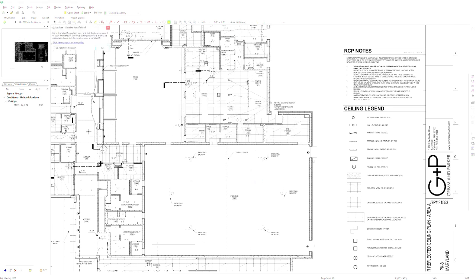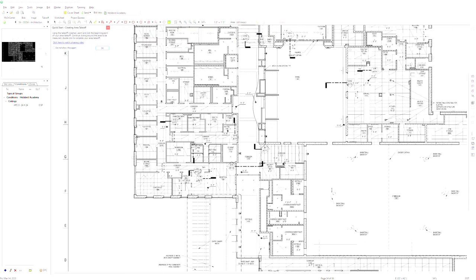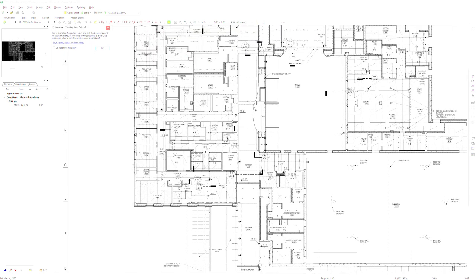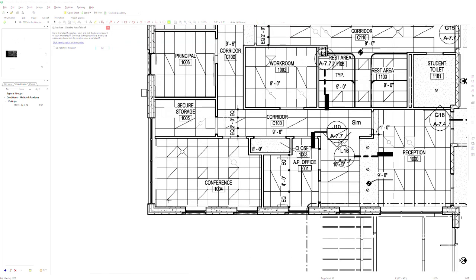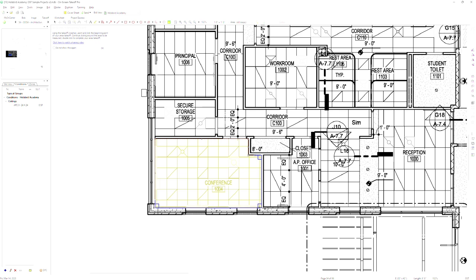All right, so now to do a little quantity takeoff. This room is large enough, so let's zoom into this conference room. And to start doing takeoff is very simple. You left click, and then you can see that now you have a measuring tool that's coming out. You would click on the corner, single click, and you can see that it is starting to put together a shape. You click at each corner and begin to make the shape yourself. Double click, and there you go.